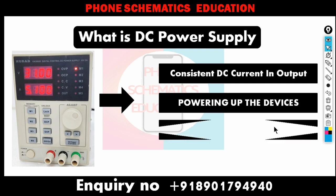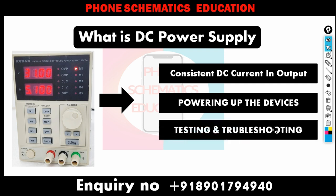Now next, testing and troubleshooting. A DC power supply is also useful for testing phones, especially dead phones or missing battery phones. Through a DC power supply, you can identify the short circuit. Also, if you observe the current behavior, you can tell whether the fault is a major fault or a normal fault.